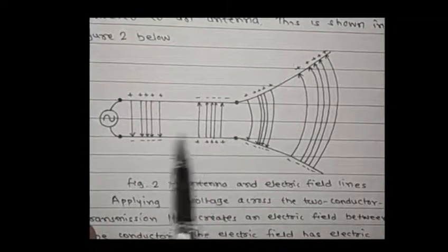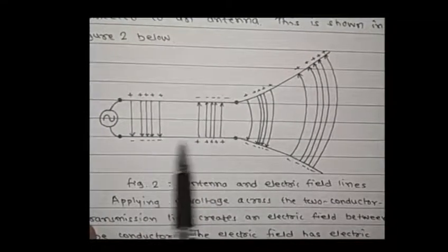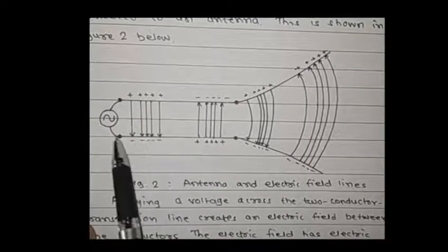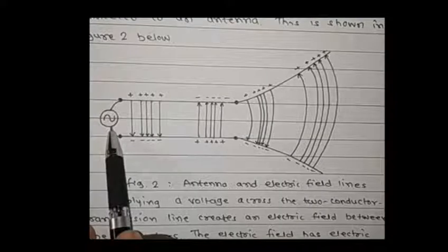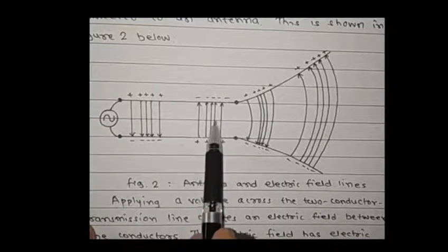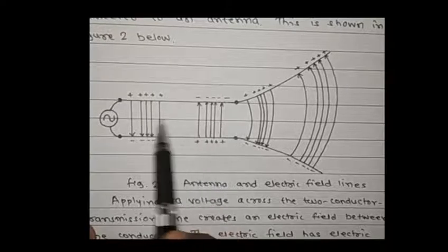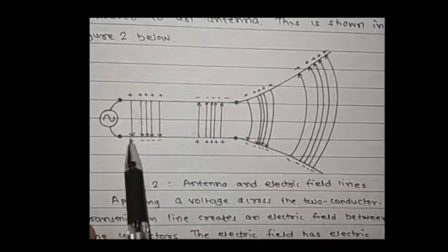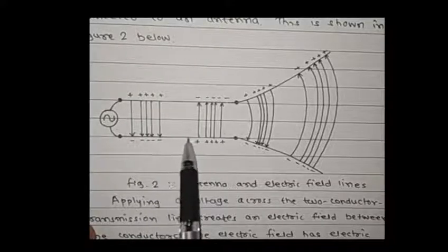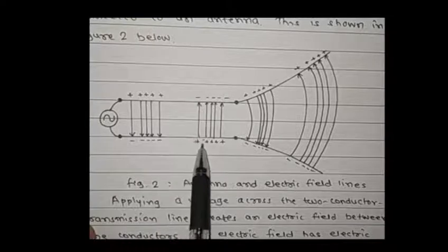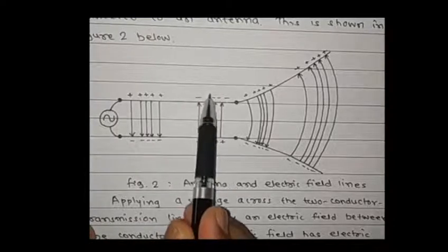These two different kinds of structures shown inside a rectangular waveguide are for a simple reason: the applied voltage source is sinusoidal, and if this indicates a positive cycle, then this portion indicates a negative cycle. In both cases, the field line originates on a positive charge and ends on a negative charge, and only the position of the charges is changed. Here we have shown positive, field lines originating on positive and ending on negative.